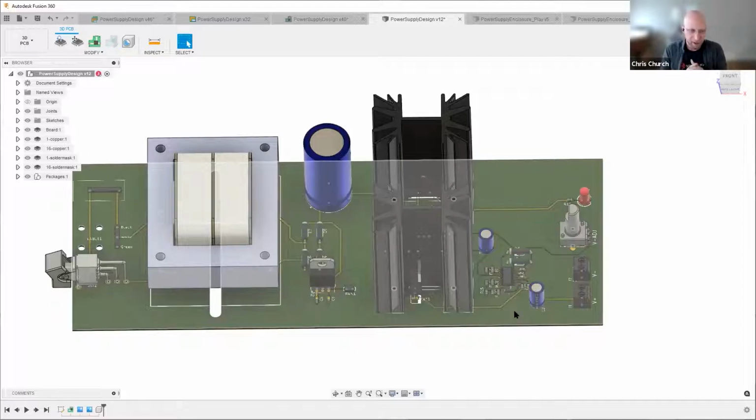So one of the questions that just came in right now, and this is very, very relevant here, is what size test points do we recommend? So typically for SMT, the minimum size we're going to want to deal with is 100 mils, 100 thousandths of an inch. That is very, very small. I would typically prefer them to be 2 or 3 times that size if possible, but we can fit a lot in there as long as they're a minimum size of 100 mil and have 100 mil spacing. We can go smaller than that, but the costs go up quite a bit.